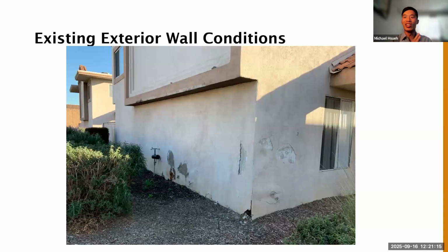This is a look at the exterior conditions of the walls. So these are existing stucco walls. This is the picture at Corona, but I think this is probably pretty representative of a lot of existing building stock that you'll see. This was at Corona, which was built in the 60s. Vera Cruz was built 30 years later in the 90s, but even that was still 40 years later. I would expect this similar kind of deterioration that you see, the finish coming off of the stucco, obvious areas that need patching, that have experienced deferred maintenance, just a big hole at this corner.